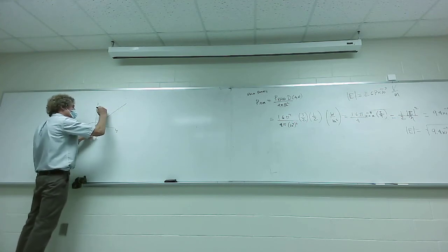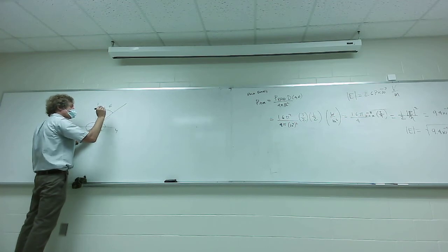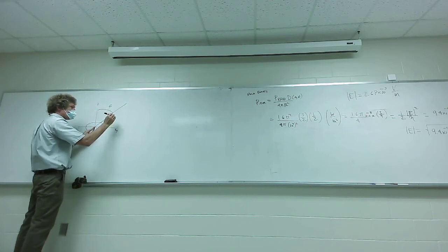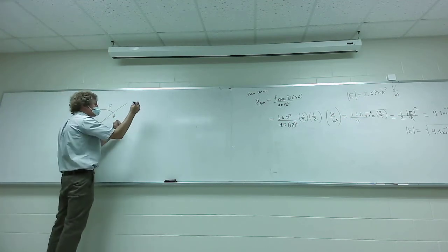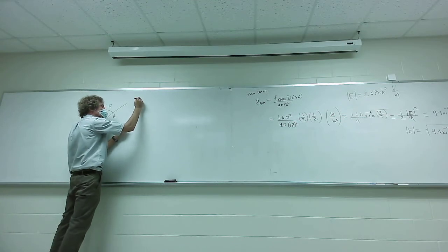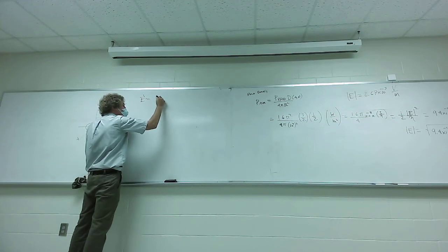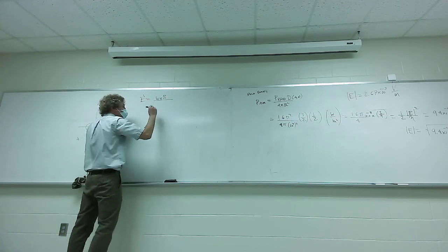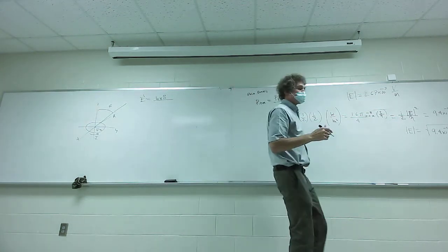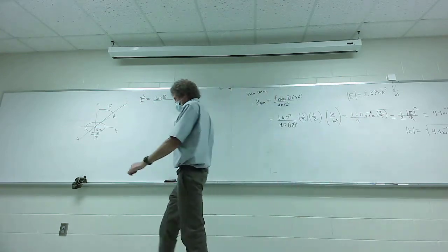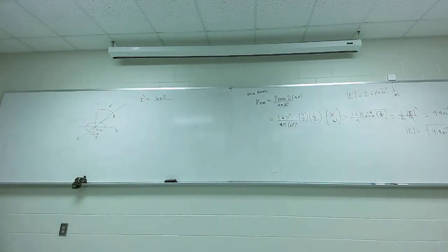But if you come out as before, at a given theta for a given range, you can find both the E field and the H field. The E field from here will be given as omega mu beta. The way Whitworth's book does it, he likes to put omega here for some reason, I'm not sure why. I like to put ratios of perimeter to wavelength, but he doesn't.